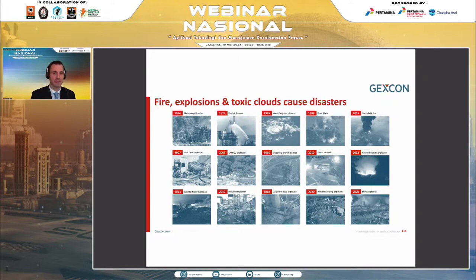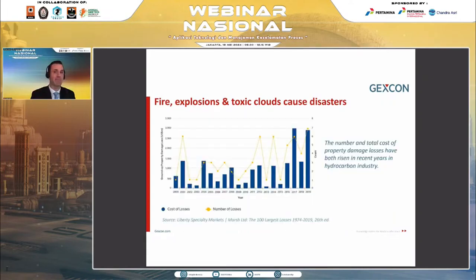Now, analytical models are great. I love them. They're fast and easy to use, with models running in a matter of seconds. They're very good when being used as a quick screening tool for a well-validated free field release or an unconfined release. As a general rule of thumb, though, they're only about plus or minus 30% level of uncertainty in consequence modeling. What they can't typically consider very well are the effects from obstacles and structures, such as the effects of an explosion pressure reflecting off a large storage tank, or say a high embankment adjacent to a release.